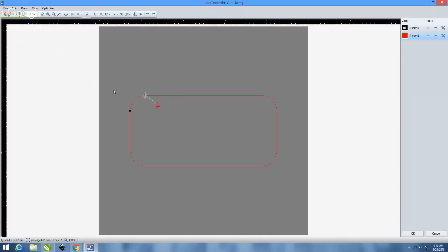So possibly you can save time with this, or maybe you have a piece of material somewhere that is higher than the material you have in your laser. So you want to avoid that piece because your laser head will hit it. So you can rearrange these laser tool paths to go around that raised piece. And there's many other applications why you would want to use that.